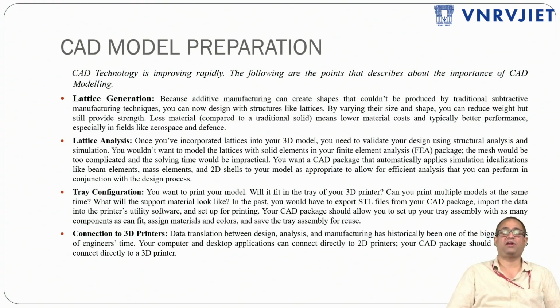on the error-free CAD model. How well are you going to prepare the CAD model? The first and foremost thing to keep in mind is lattice generation. The CAD model should be worked out with lattice structures. If you work with lattice structures, we can reduce the weight, provide more strength to the object, and also less material is utilized. And after generating the lattice, we need to talk about the lattice analysis.